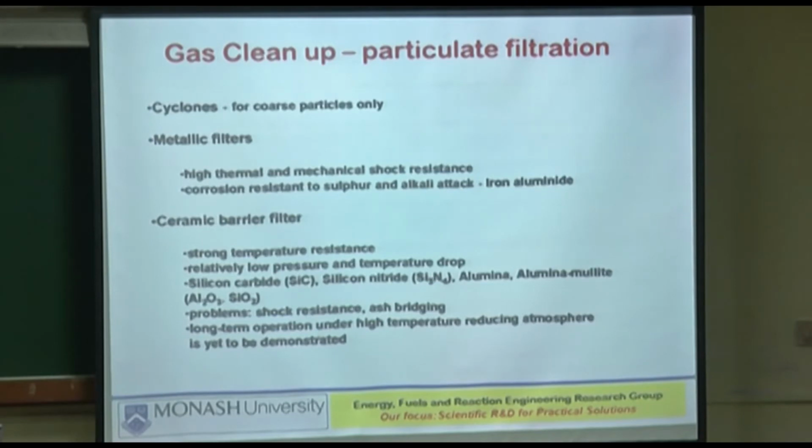But they have a problem. What is the problem? That they don't like pressure shocks. If that be the case, they crack. So pressure itself is not a problem, but if the pressure swings, so if you're running at say 30 bar, that itself will not be a problem.